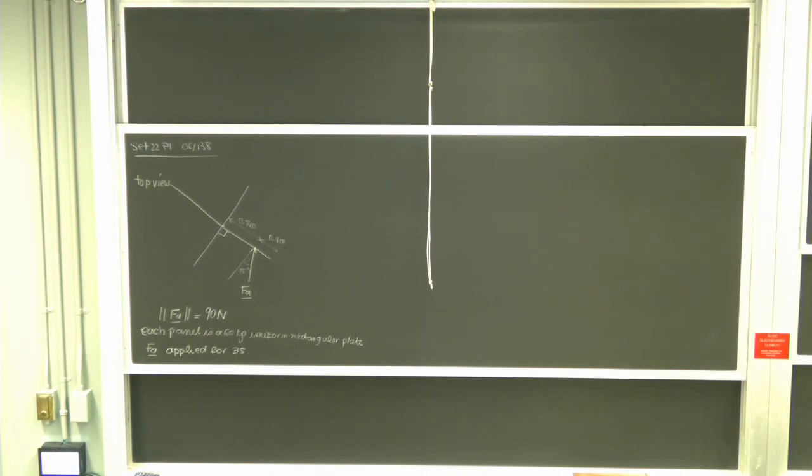Okay, so how are we going to solve this problem? Any ideas? Yes. With the first equation for angular momentum about the center. Exactly. So in this problem, if we take our system to be the 4 panels, it happens to be that the origin or the center of mass is basically a fixed point. The 4 panels are rotating about their combined center of mass.